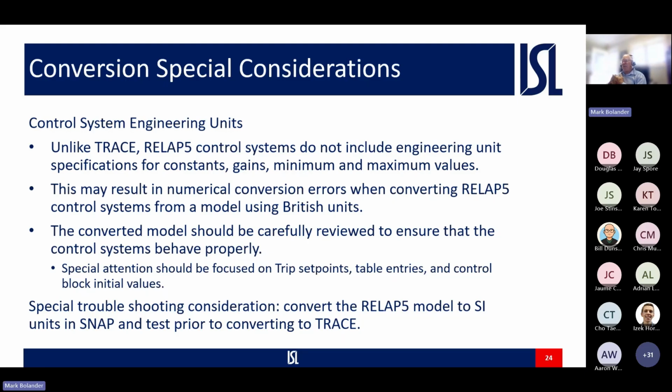Okay, and that brings up the issue of if I've got a RELAP5 model that's in English units, do I convert that model to SI units before I do my RELAP to TRACE conversion? And does that help anything? And the answer there is not necessarily, because the constants and gains are unitless in RELAP5. Does that make sense to you? Yeah, thank you.